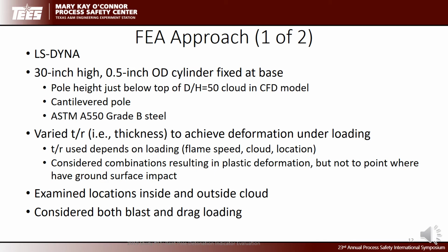That is, if we had a pole that wasn't undergoing any deformation, then we would make the thickness a little bit less so it would deform under the prescribed loading. Conversely, if we had a pole that was slamming into the ground, well, we'd make it a little thicker. What we wanted to see was pole deformation, and whether that pole deformation was exhibiting continuous curvature or not. As I think I mentioned earlier, we looked at locations both inside and outside the cloud, and we considered both the blast and drag loading.